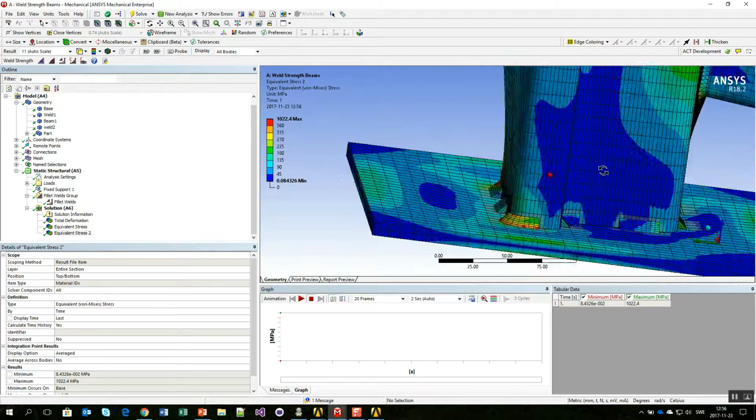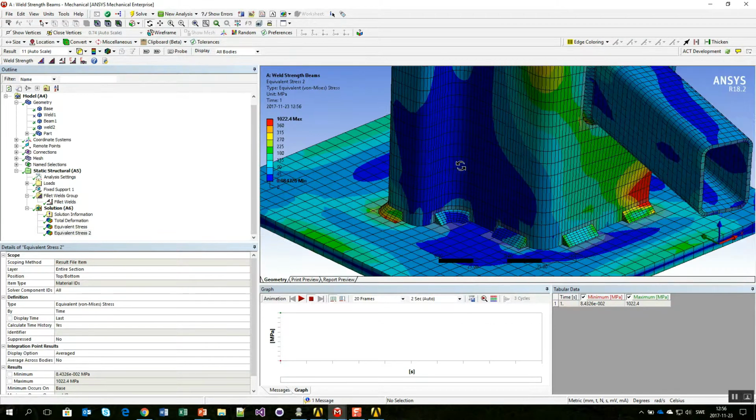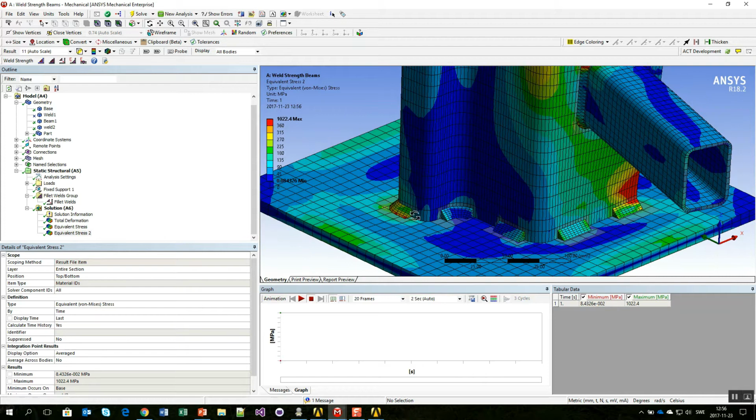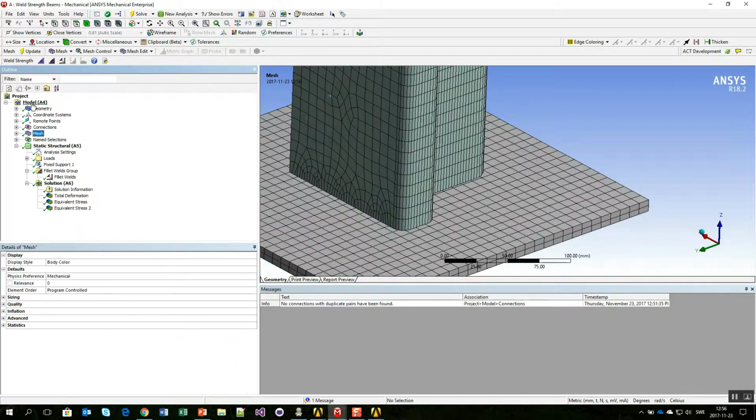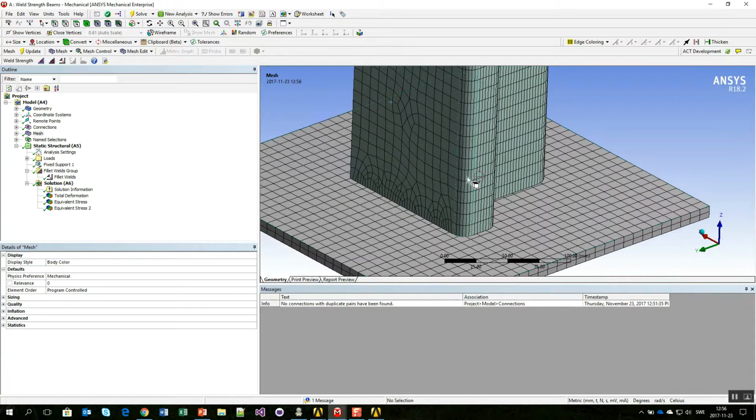And we see here the updated weld mesh. So the big benefit, since it's not geometry based, is we don't have to remesh the model, or there is no geometry update needed, so everything else in the model stays exactly the same. The weld is treated as a load object.